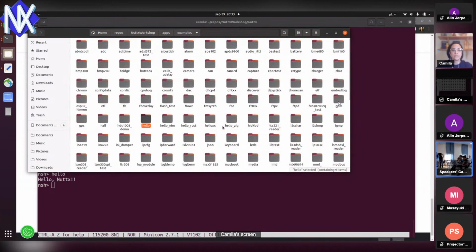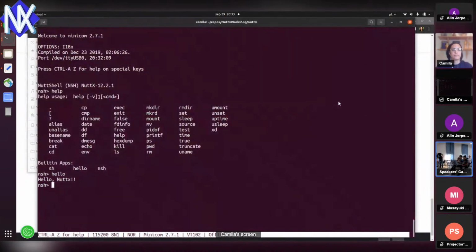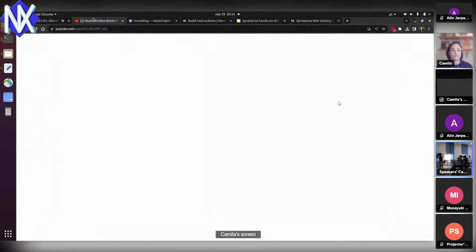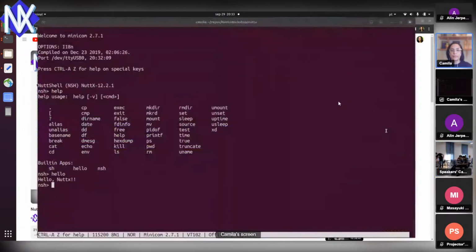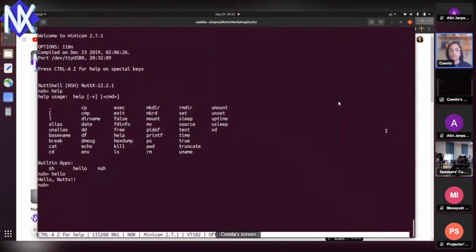Camila, we have a question in the YouTube chat from André Almeida. Camila, to try another example, is it necessary to repeat those steps? Yes, to try another example, you need to configure the board. Here, I've configured it for the hello example. So say I want to configure for another example, then I have to reconfigure, make again, and flash again.